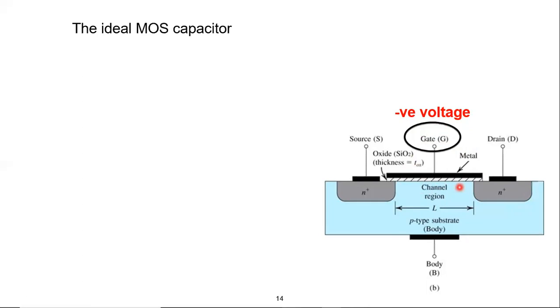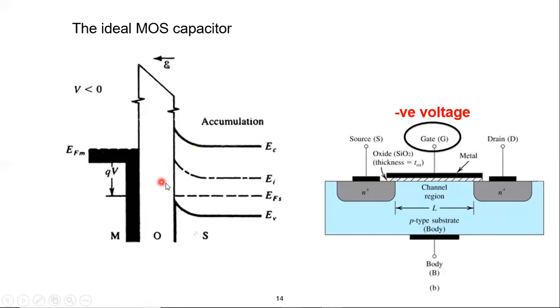So in order to demonstrate this impact on the energy band diagram, we will have an energy band diagram like that. First of all, it is no longer thermodynamic equilibrium, as EFM and EFS are not aligned. Second, as you know, we can measure the doping by measuring the distance between the EFS and the valence band. So as we go toward the border, the material becomes more p-type, because this is a negative charge. So what will be accumulated here is holes. So the material will be more p-type going toward the border here.